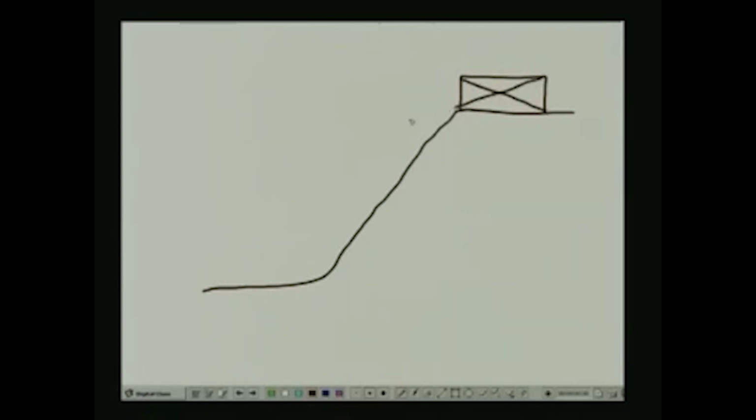And then there could be other causes, like there is a pre-existing stable slope and we construct a very heavy structure near the top of the slope, and this also is going to increase the destabilizing force, and this in turn could lead to a failure in this manner.